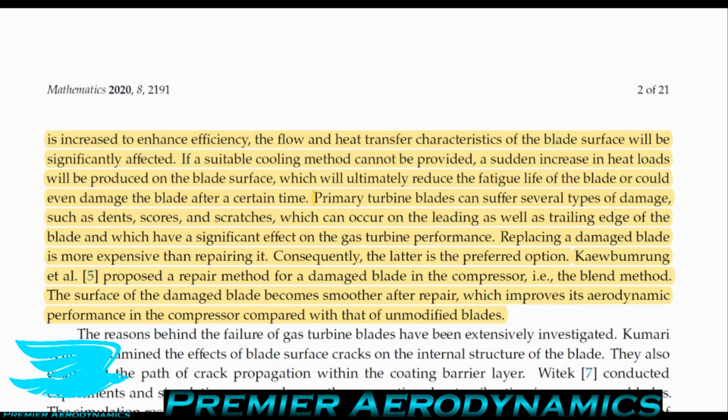So you can have a longer blade just by spinning it faster because of centrifugal forces, which produce forces on the blade and expand it through these dislocation lines. And if you have the wall of your cowling or your shroud very close to the blade tip, these tips can actually start hitting the outside, these shrouds or cowlings, and wear them away or even damage the blades. So that's one way of making a blade out of one crystal, so it doesn't have these dislocations, and that means it won't expand in that same sort of fashion, and then you can have a safer blade.